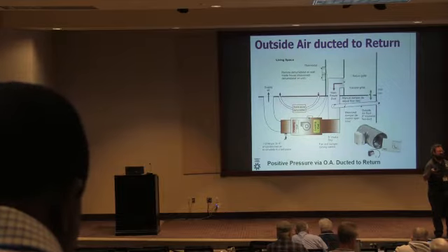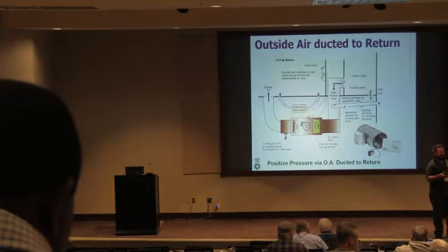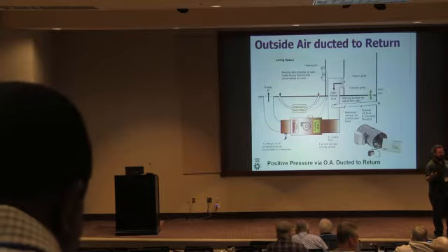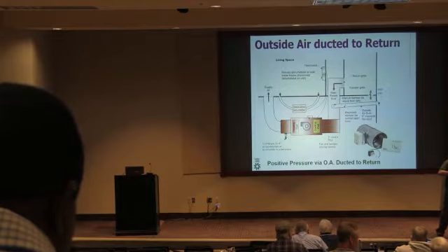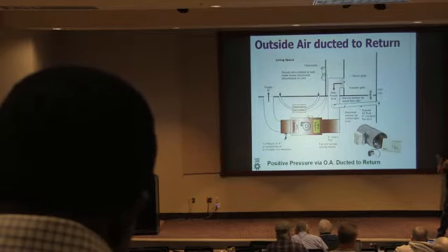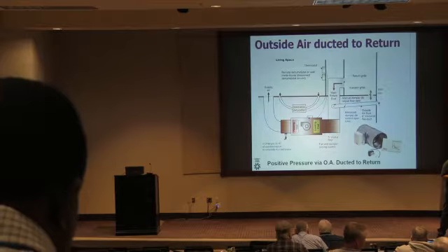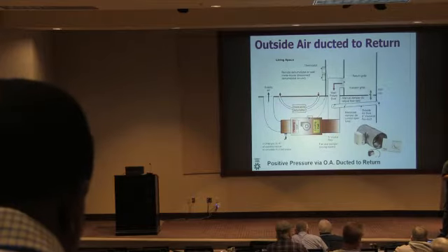I prefer systems where they don't try and pressurize hallways and depressurize units and then use transfer grills or something, because you can't possibly balance that system. You have no way to know which unit is getting how much air.